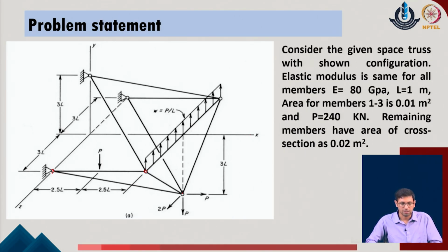Now a simple example where you can implement these problems is a simple industrial shed. If we look at the industrial shed, we can consider that one part of the member trusses has been identified, say something like this. In many cases we consider that uniformity of the bay areas exists, so one simple truss as a plane truss can be analyzed.